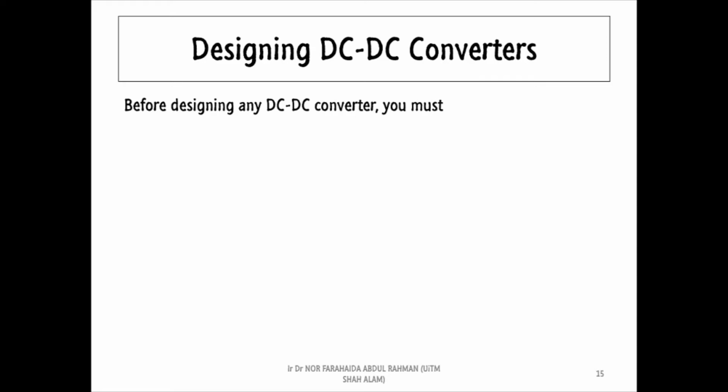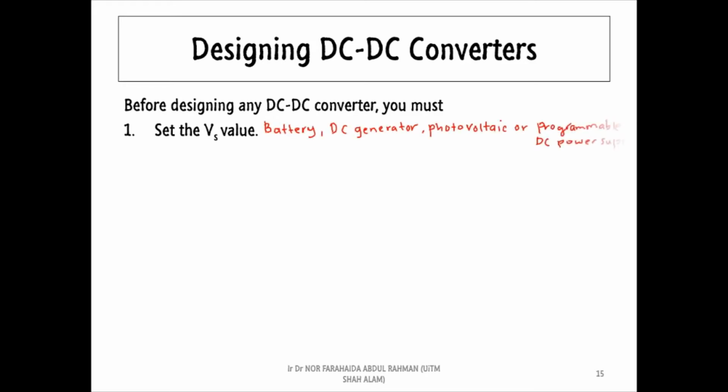In this video, I will explain the basic procedures to design a DC-DC converter. Before designing any converter, you must set the input voltage value. It depends whether you are using a battery, DC generator, photovoltaic, or programmable DC power supply.